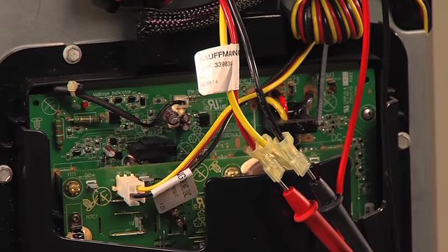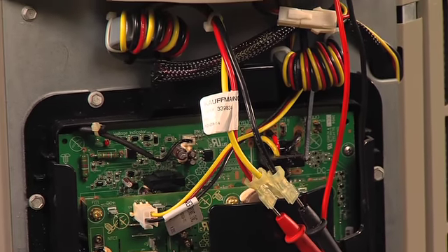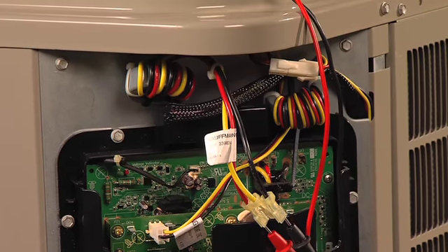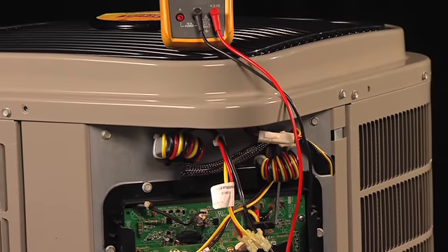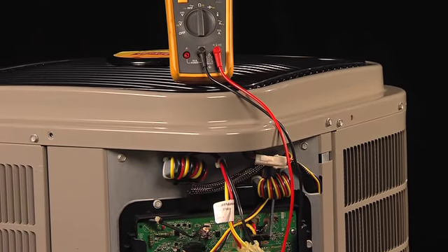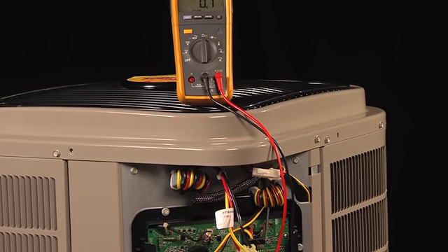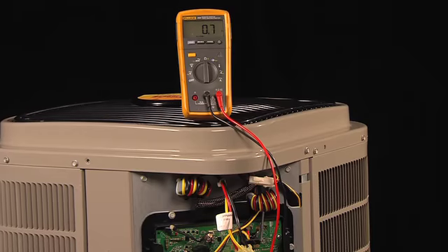A multimeter should be used to check the winding resistances in ohms between the phases or ground of the compressor and fan motor, if they are suspected of being defective. The service manual has the appropriate resistance values.